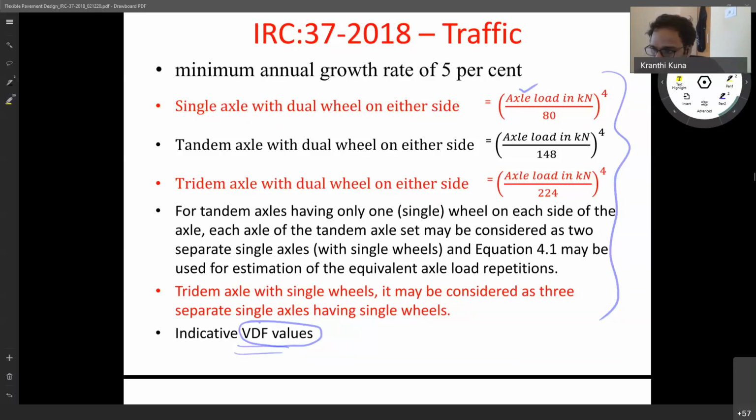But the other two models for CTB we borrowed from Austroads. When they developed those equations, their contact stress was 0.8 megapascal. That's why we have to run the analysis for 0.8 megapascal. Otherwise, running it at 0.56 is not what they have calibrated for. That's why we have two different models.